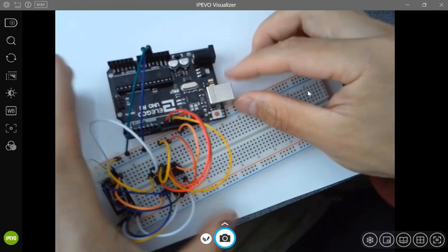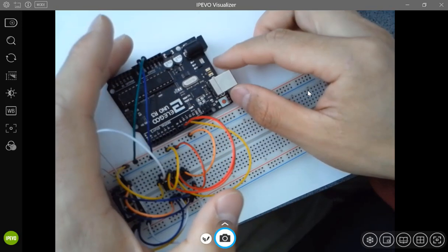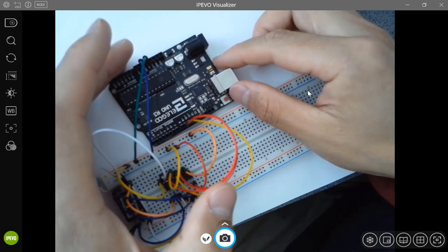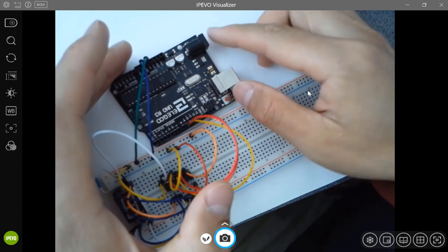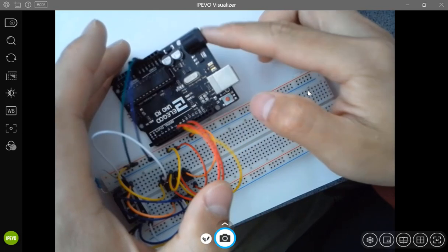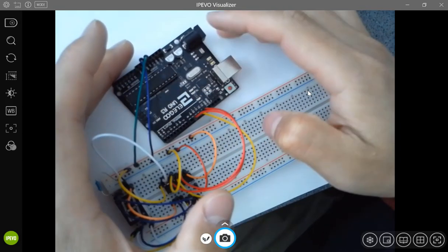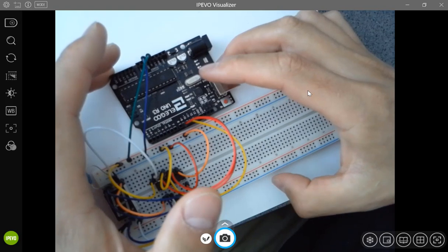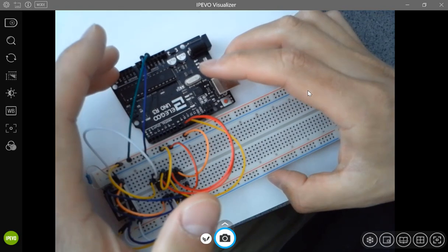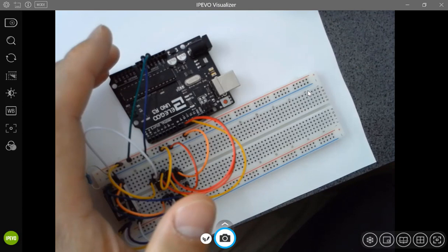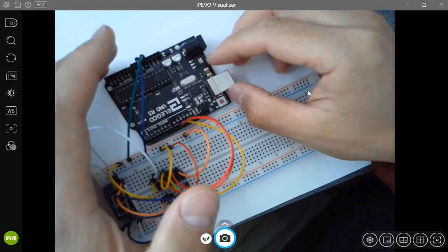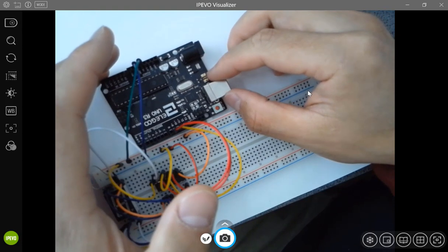But for example, is it possible that the voltage reading here is 4 volts to 12 volts? Is that possible, from 4 volts to 12 volts for this thing? When I'm trying to power up my Uno, would 12 volts work? You probably want to take a look at the input voltage rating for the voltage regulator you placed on your PCB a couple weeks ago. Remember the name of the voltage regulator?